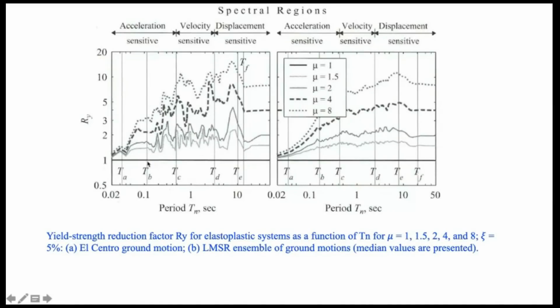If ductility is 1, Ry is 1 over all vibration period values. But if ductility is 1.5, 2, 4, or 8, Ry changes accordingly. Even if you introduce a small ductility demand of 1.5, Ry changes to quite large values from 1. And Ry increases with increasing ductility demand.